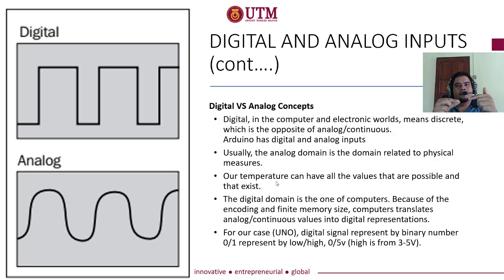You must connect your temperature sensor with an analog input port, because this analog input port in Arduino has a specialty in changing the analog signal into a digital signal. So now it can process things, because once it's changed into a digital signal, the CPU inside your Arduino can understand the value in voltage that represents the temperature of the environment. So that is how it looks.